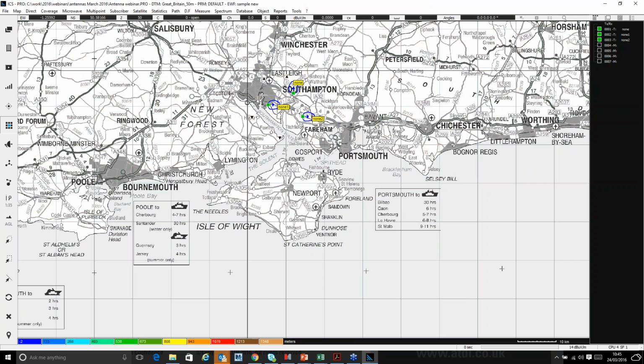Okay, so you can see here the form of the antenna pattern, the horizontal pattern, is shown, and I've got this arrow that points for the azimuth direction that's been applied to these as well. I hadn't changed those, this just happens to be the directions that are already applied. But it's a nice way, particularly if you started with omnidirectional, of visually being able to see, and if you've got multiple sectors on here that are equally applicable, that you've made that change, and that's obviously taken for all of those stations that you're interested in.